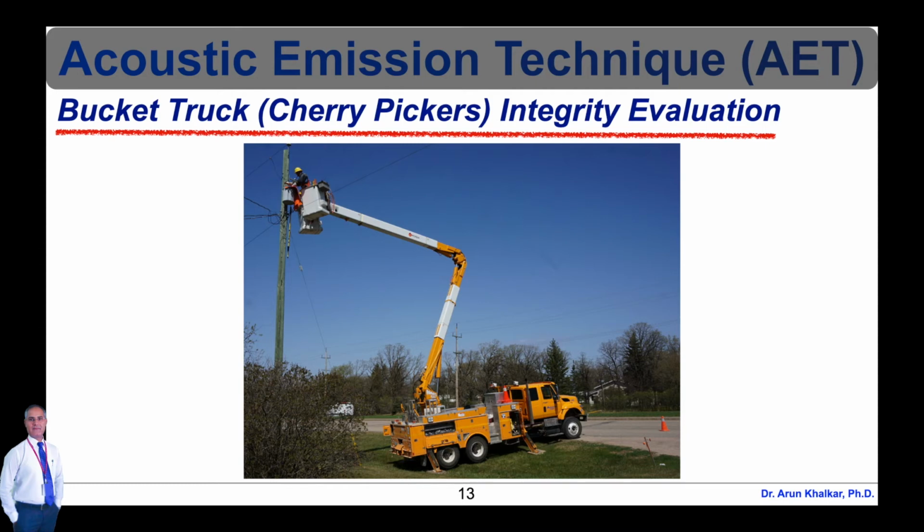Although originally intended to examine only the boom sections, the method is now used for inspecting the pedestal, pins, and various other components. Normally, the AE tests are second in a chain of inspections which starts with visual checks. If necessary, follow-up tests take the form of magnetic particle, dye penetrant, or ultrasonic inspections. Experienced personnel can perform 5 to 10 tests per day, saving valuable time and money along the way. The procedure for examining insulated aerial personnel devices is shown in this picture.